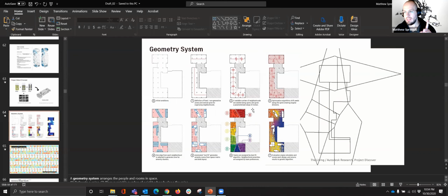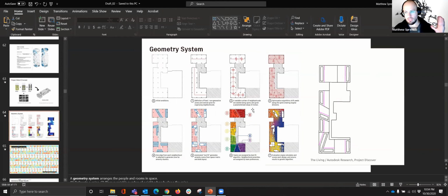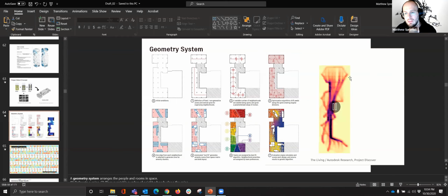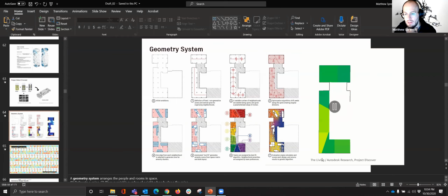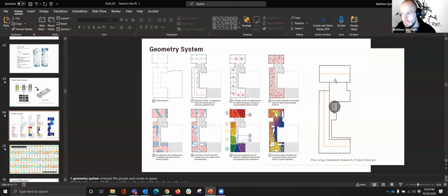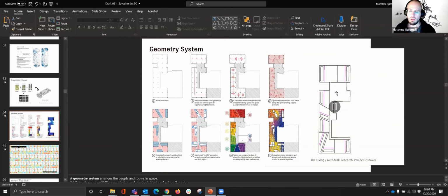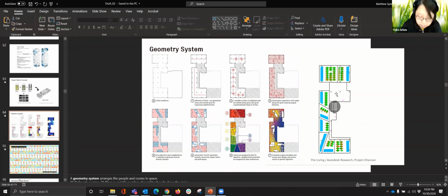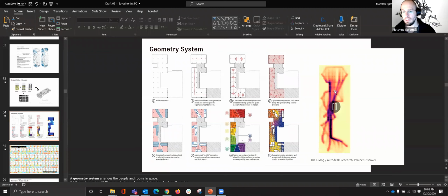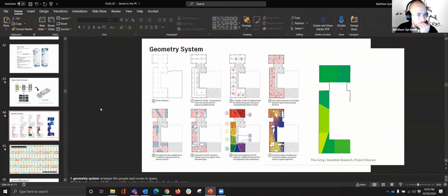That's usually one team's task. They just experiment with the geometry. The only special consideration for generative design is to make sure that if the algorithm runs automatically, it will not have a null condition. So this means that it will not produce geometry that is going to result in a bad value later. This could be like a value of 0 or a null condition in both Dynamo or Grasshopper.